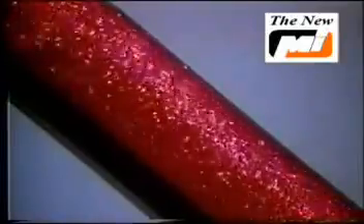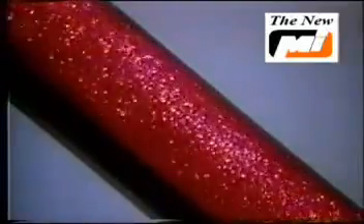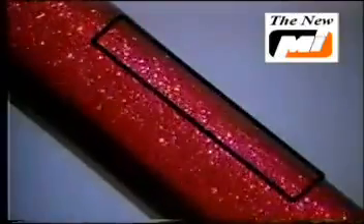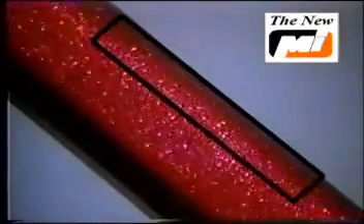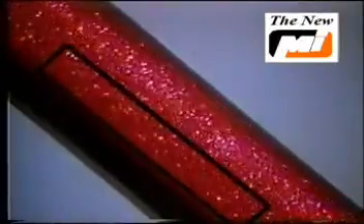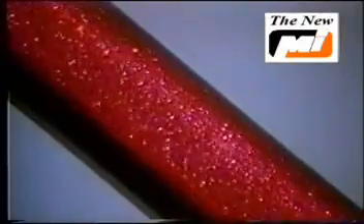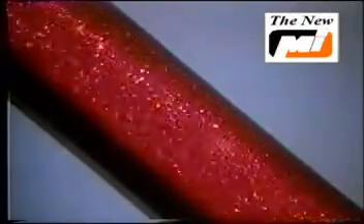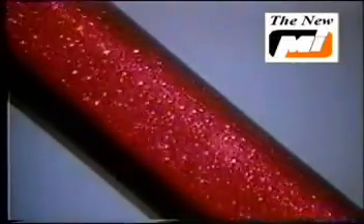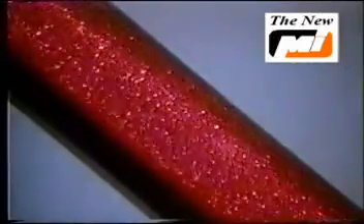One phenomenon of cuttings behavior in angled wellbores, called boycott settling, shown here at 45 degrees, shows the clarified layer along the upper side and the slump along the lower side of the tube. This boycott settling causes some particles to move upward with the flow stream. Others are momentarily suspended, while still others form a bed along the bottom of the hole and slump opposite to the direction of flow.